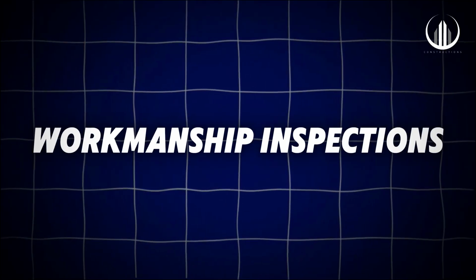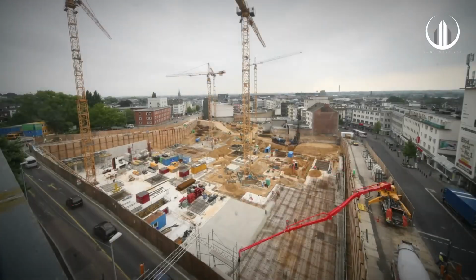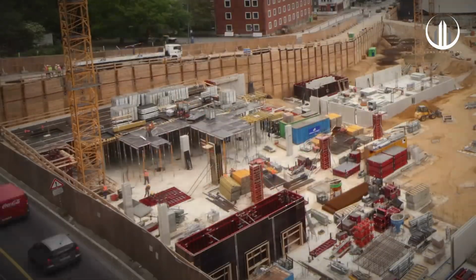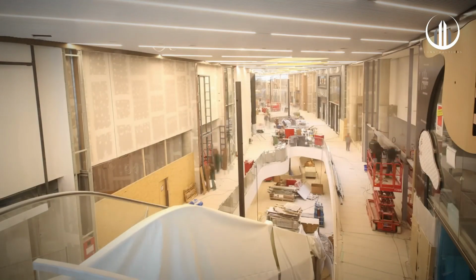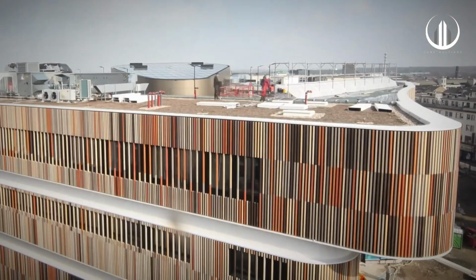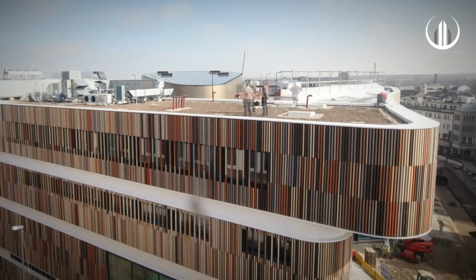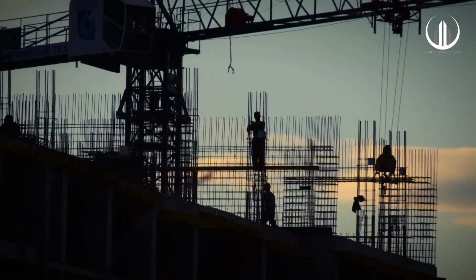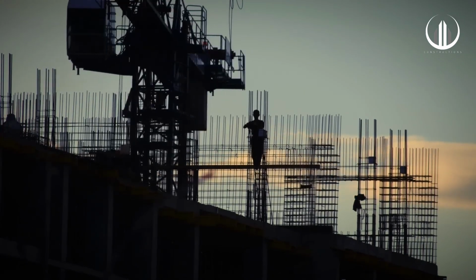Workmanship inspections. Inspect ongoing work to ensure that construction methods are being adhered to and that the work meets the required standards. Final inspections. After construction is completed, conduct a thorough final inspection to ensure that all aspects of the project meet the original specifications and building codes. Any discrepancies should be addressed before the project is handed over.